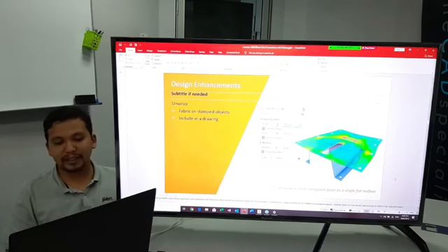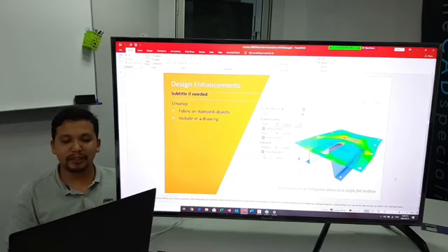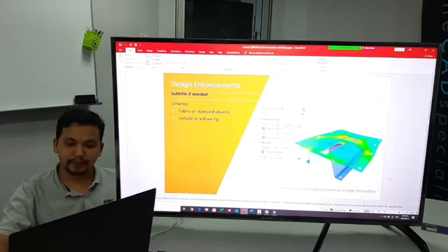For example, this is to determine a fabric pattern for flattening stem objects. So this unwrap function does not use the bend calculation to flatten the selected face.